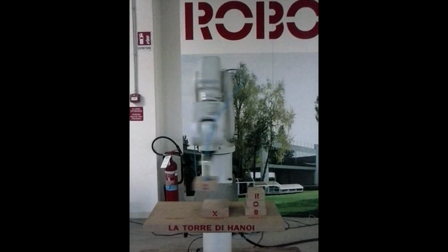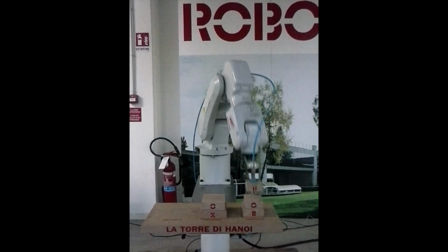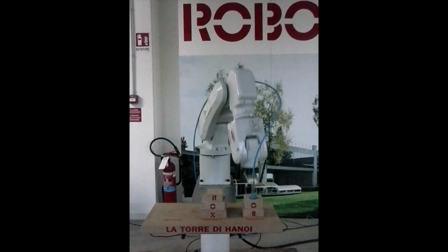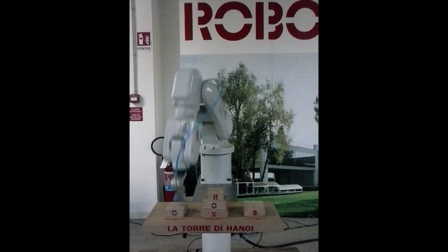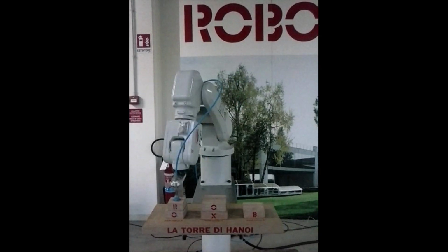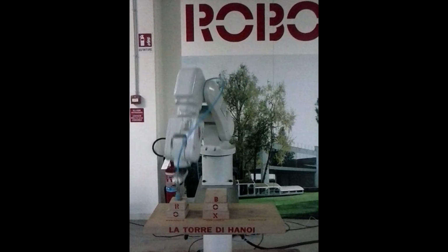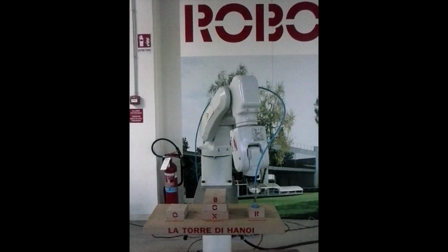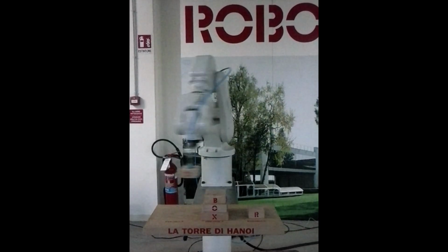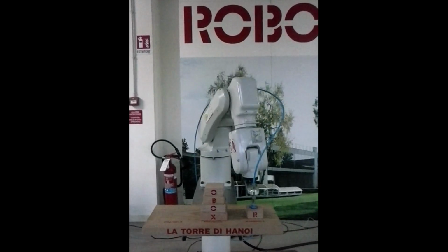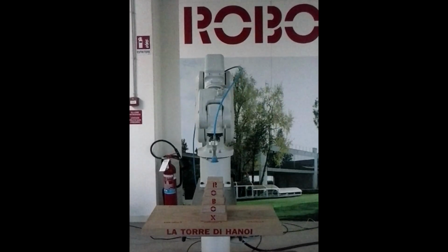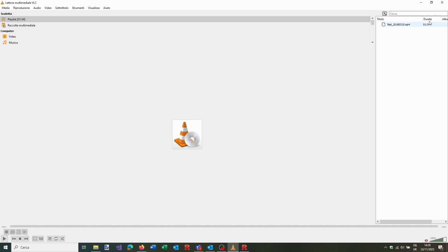Of course, the joint motion will always be possible because every motor will move along, not caring about the others and also not caring about the trajectory of the whole system. A Cartesian movement may be a little more problematic since it can go through some singularity or through some not allowed points.